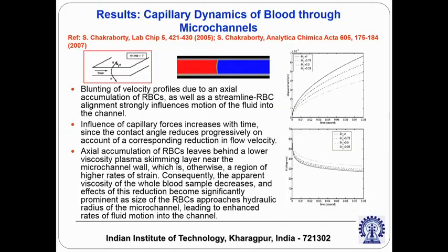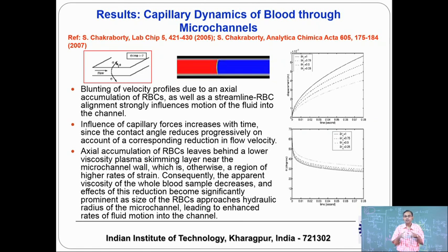So, with all these things, it is possible to make a mathematical model which shows how in a microfluidic channel you can transmit blood by using surface tension. This becomes one of the basic premises of designing microneedles and medical diagnostic devices, which primarily work on capillary action. For example, medical diagnostic devices on paper substrates, on which capillary action alone drives the sample.